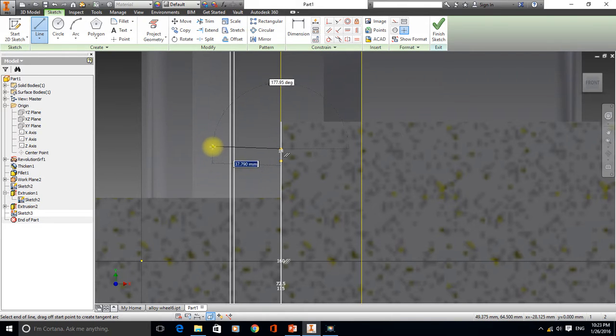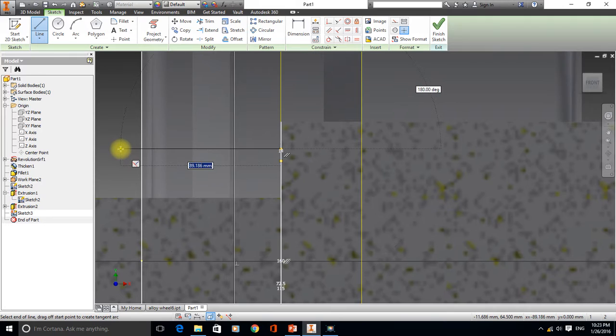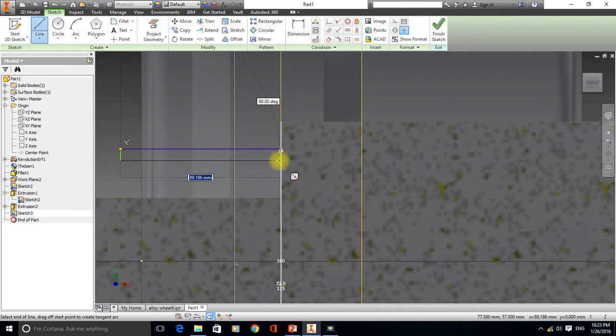And I'm now going to drag out some lines to create my holes. This doesn't matter how long it is. Now, I've got polar tracking here. I don't know if anyone can see it. It's snapping to 7mm, and if you look to the right of where my cursor is, there's a dotted line tracking back. And that is basically snapping, so I've now got two lines parallel, 7mm apart.